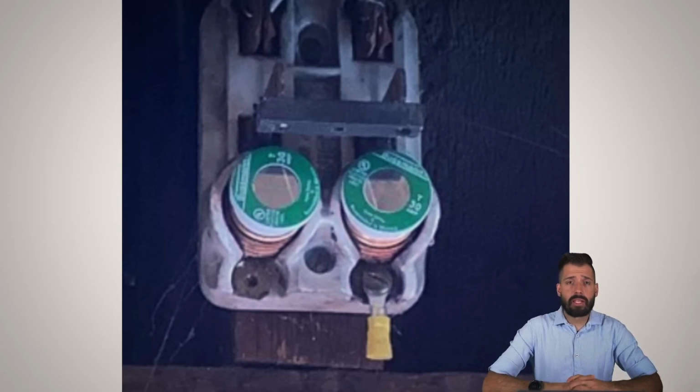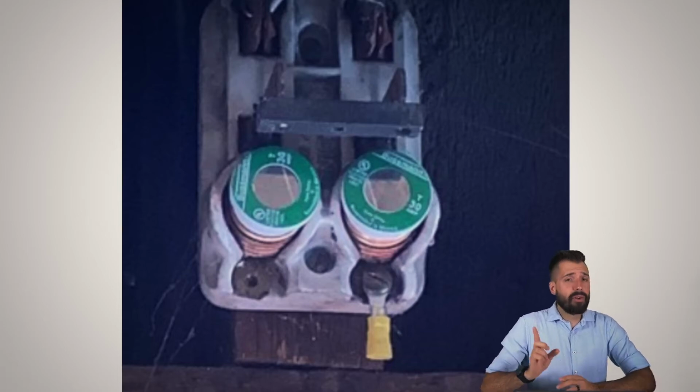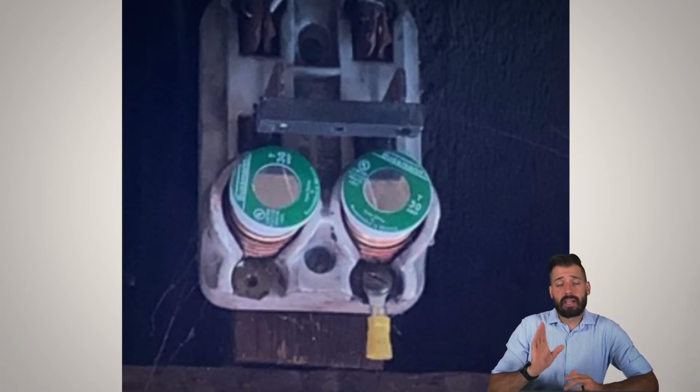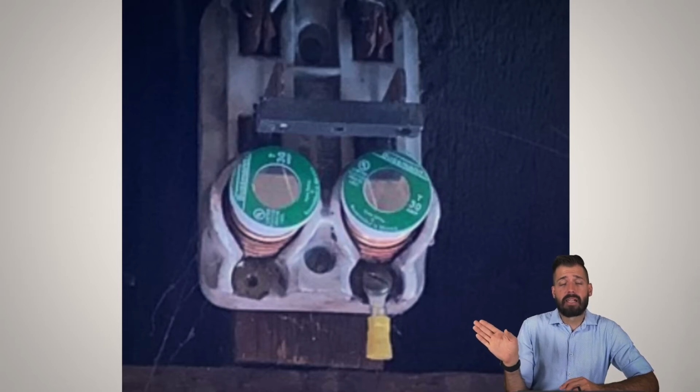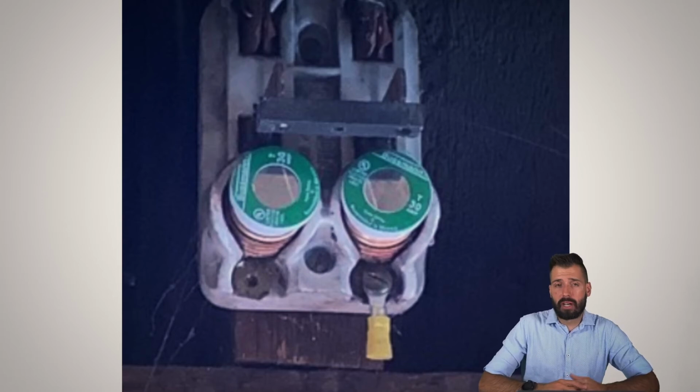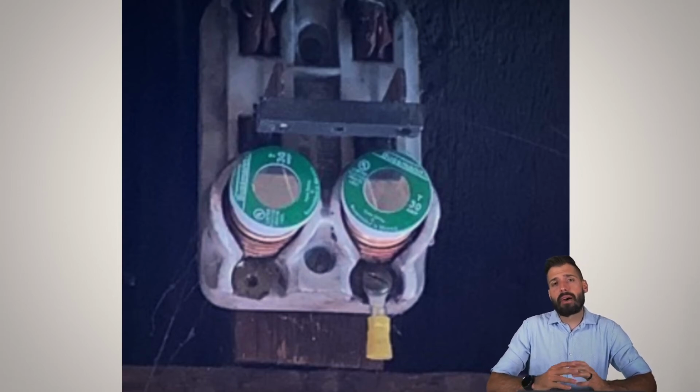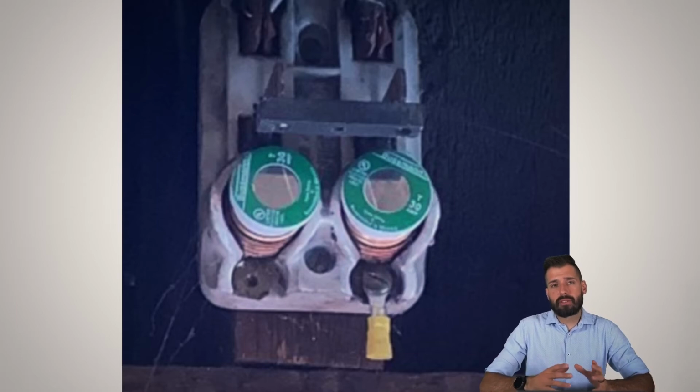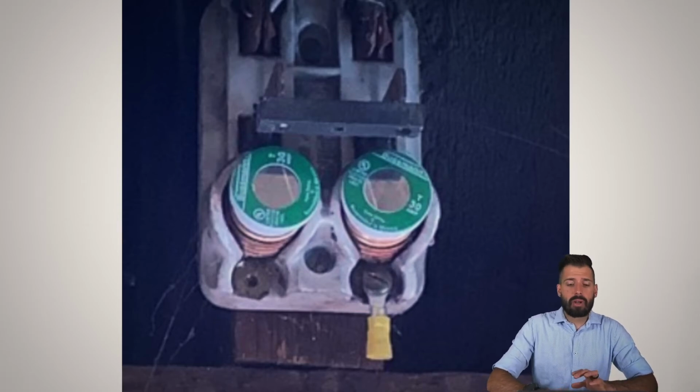That's all well and good, and that's pretty easy to understand, except do you see some of the issues that we have with this particular unit? Now, again, I don't know if it's connected or not at the top, but down here it looks like it's disconnected. But can you see how I could just reach out and grab almost anything, and that would more than likely cause me to be electrocuted? So anytime we have exposed electrical conductors, we want to make sure that they are covered up, whether inside of a junction box or with a proper cover on things. We really want to make sure that people are safe.